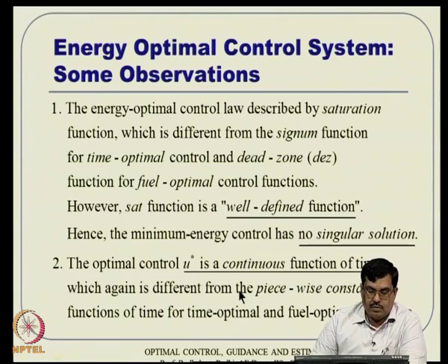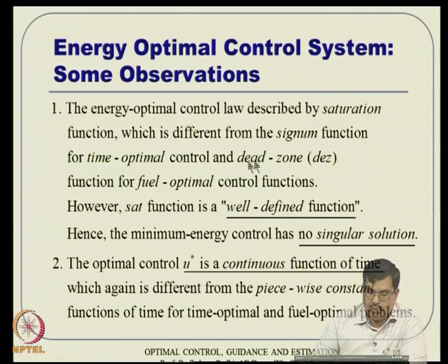Now, some comments or observations. First of all, the energy optimal control law is described by a saturation function, which is different from the signum function for time optimal control. That is the bang-bang control, defined by the signum function, and it is also like a dead zone function for fuel optimal control problems.